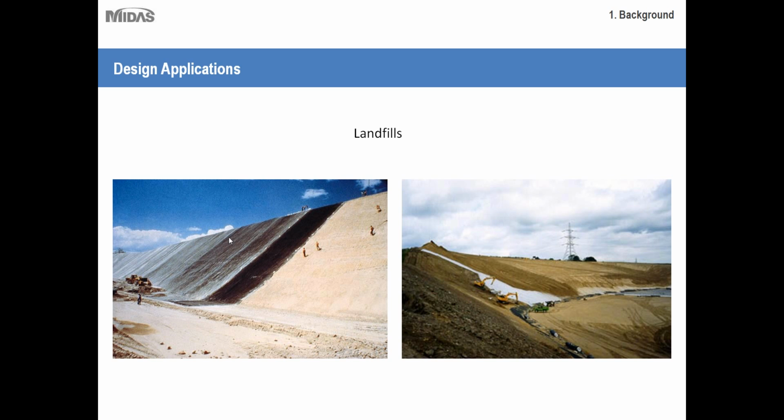If you're working in an area with large amounts of rainfall, what these will do is keep the water from seeping into your slope and compromising its stability. But if you work in an area that's relatively dry, then you wouldn't really need to worry about that. So once again, your project area or site conditions determine how you would design your slope. In addition to the soil you're working with, another key factor to take into account is rainfall.